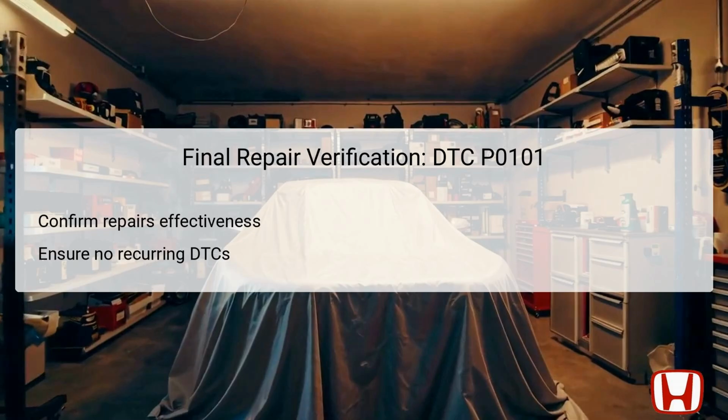Ensure that all repairs performed on the MAF sensor or related components are effective by monitoring the vehicle's performance over time. It's essential to verify that no recurring DTCs appear, indicating that the problem has been resolved. A successful repair will lead to normal engine behavior, including responsive acceleration and a steady idle. Additionally, make sure to check that related sensors and connections are secure and functioning correctly. Consistent monitoring after repair helps ensure long-term reliability of the system.